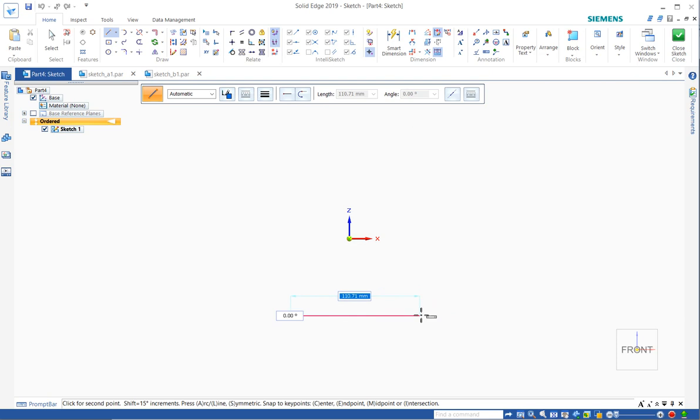So as you draw, IntelliSketch is finding the horizontal. We talked about this in one of the first sketching activities, but I'll just recover it. I'll tap A. This little circle with a cross is design intent, so come back in there and make sure you get your, and there again, the alignment indicator is finding another element.